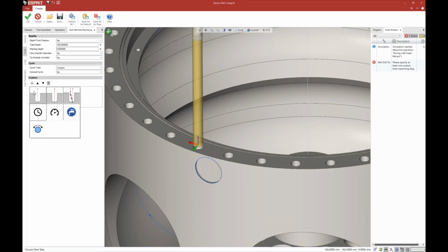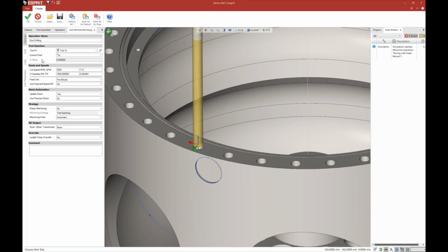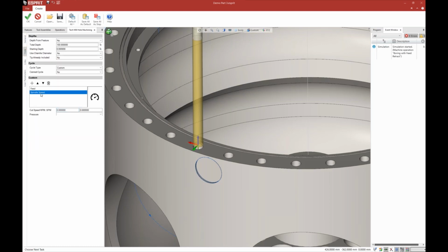So first thing we want to do is, this is going to be a deep hole drilling cycle. First move is going to be a feed move. This is a metric file, so I'm just going to say 2,500 here, millimeters per minute. We'll go down to a depth of 25 millimeters, so about an inch. And that's going to be the first move. Then, once we reach that depth, I want to ramp up my spindle speed. It starts with what's defined on the general tab here, this initial RPM and feed rate. And then once I have this spindle speed here, let's ramp that up to maybe 5,000 RPM. So we'll go to 5,000.